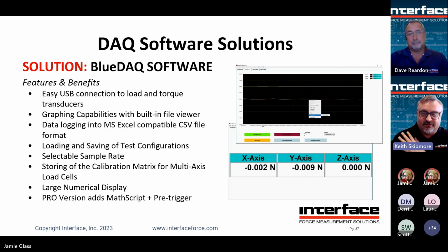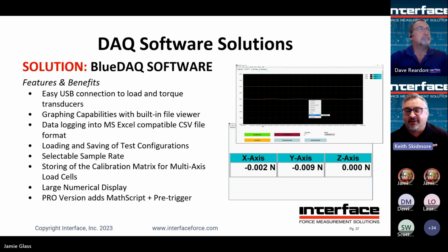It allows you to manage the matrices, load them in and out of the BX8, and select multiple sensors stored internally in the BX8. And one thing to note, the BX8 runs on its own, so you can use the Blue DAQ to set up the BX8, load the matrix, have the 6-axis sensor running, configure the analog output so that the analog outputs are scaled and actively following the 6-axis measurements, and then you can just disconnect the PC and the BX8 will just sit there and run on its own, still running its analog outputs, say to a control system or something.